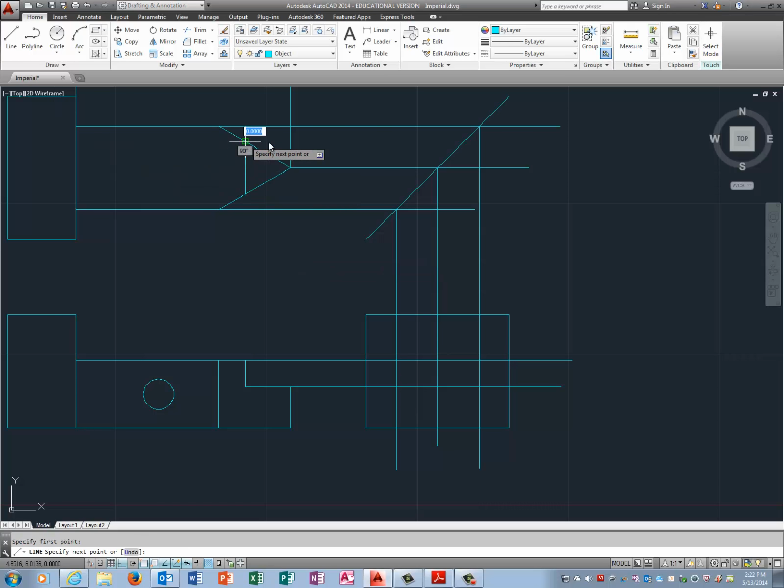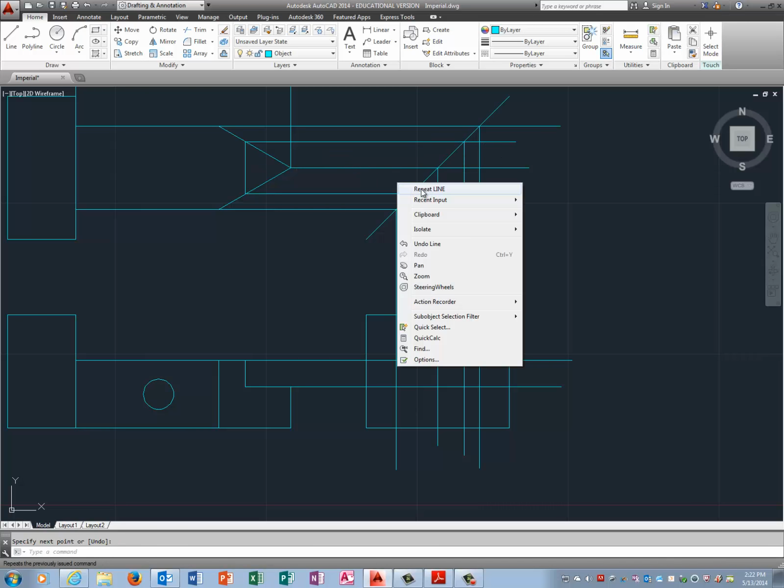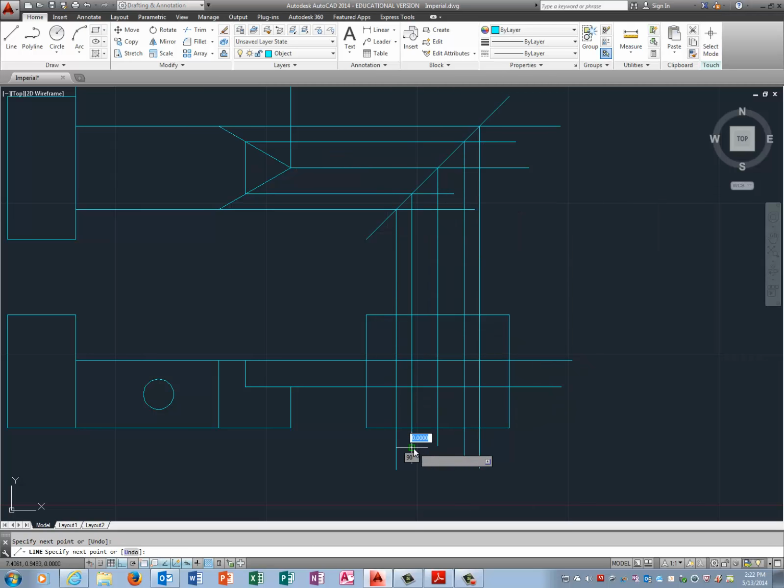He's got to come down this way too. Okay, and then get the other side. Oops, midpoint snap wants to be a midpoint snap, and we don't want it to be a midpoint snap. There you go. So you can see there are these two L features here, and then the box that goes around them. So let's work on trimming those out.